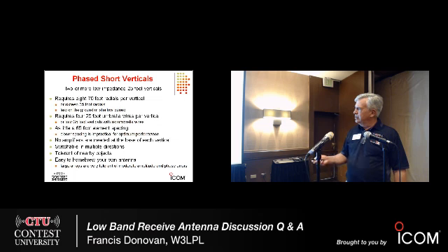You can use as short as 65-foot element spacing in a 4-square array. Smaller spacing than that is really impractical unless you have precision instruments, because the equal amplitude and phase matching becomes extremely critical with small spacing. So unless you really can't get at least this much spacing, and unless you have really good lab instrumentation, I don't recommend trying an antenna smaller than this.